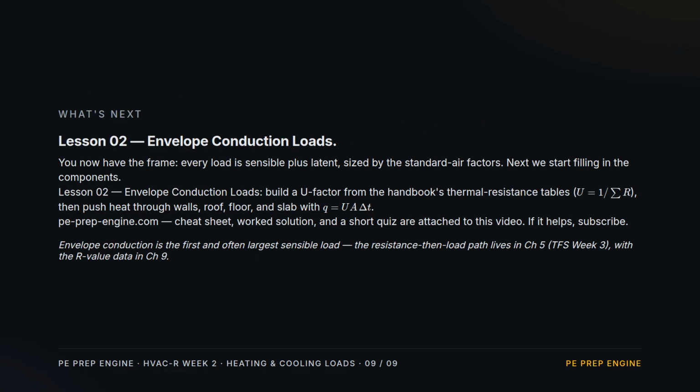Next, Lesson 2, Envelope Conduction Loads. We build U factors from the handbook's resistance tables and push heat through walls, roof, and slab with Q equals U, A, delta T.